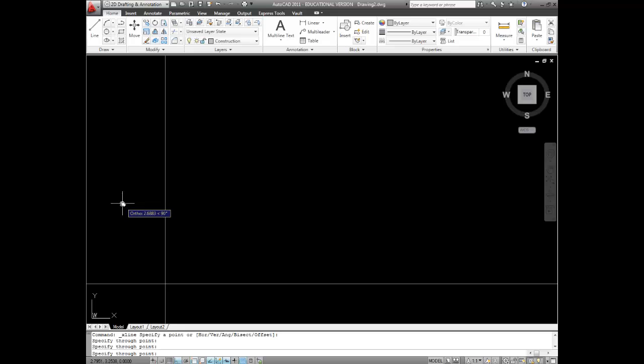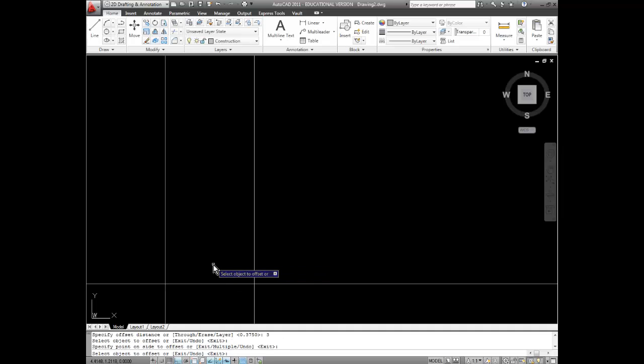So now let's add those dimensions for our bounding rectangles. The first tool that I'm going to use will be the offset tool, and I'm going to establish the length of the part, which is 3 inches. Go this way, 3 inches. Now we need a space. Well, let's do the top of the front view. So that one will be 1 inch. Offset it that way. Now this will be our front view.